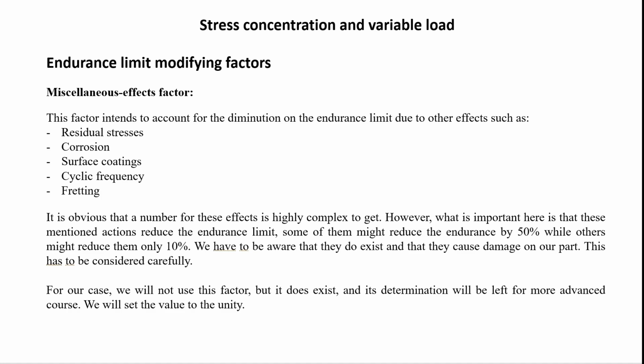Then corrosion affects the fatigue limit of your part, because corrosion creates pits or pitting on the surface of the material, and pittings are kind of equivalent to the surface finish factor, since they are the door for crack initiation. Coatings, if you have coatings, could improve or could deteriorate the capacity of bearing load in terms of fatigue design.